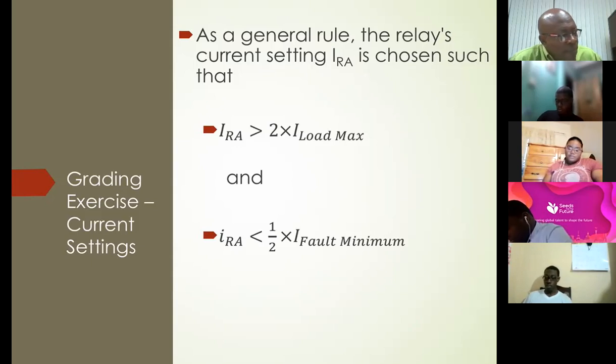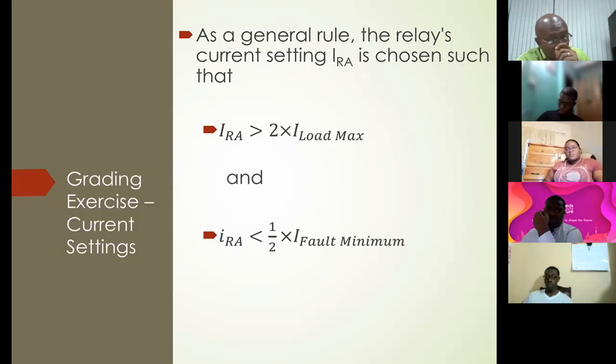Among them, during maintenance, depending on the bus bar arrangement that you have, you may need to shift load within the system. So you shift load from one transformer to the next while you're doing switching operations. Now, you wouldn't want the system to shut down simply because you have transferred load. So this sort of criterion allows you to carry out certain activities without disruption.